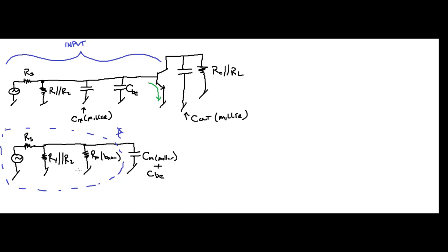So when you Thevenize something, remember for resistance, you replace your source with a short, just a wire. So when you do that, RS is also going to ground, isn't it? So all these resistors are in parallel and they're all going to ground.